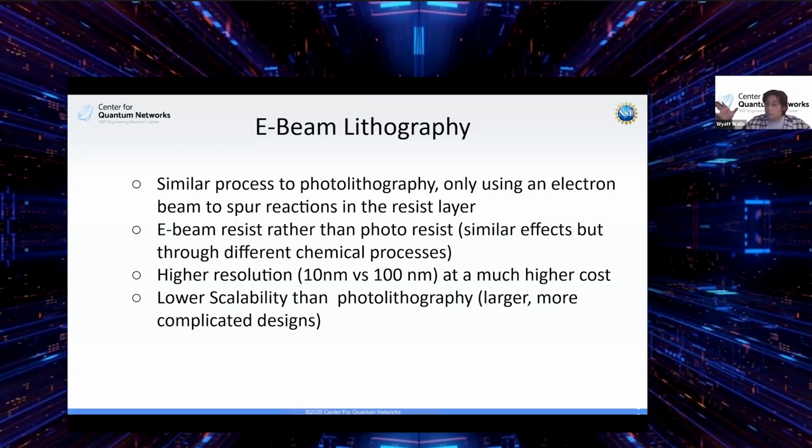So if you're trying to make a very long, very large structure, something like a maskless photolithography, the stage usually is allowed to move. The write head that illuminates the photoresist is usually able to move pretty far. With e-beam lithography, you get that resolution. However, it does a very small area and then it has to move over and do another very small area, and moves over, and it takes a very long time to do that. There was a design I've done that took me about 5 minutes doing photolithography. It took me over an hour and a half with e-beam. It was almost the exact same design.